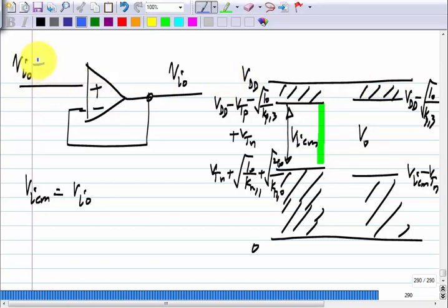Now, in this particular case, you have to look at this again, now we apply a signal. So, Vi0 plus Vi, what will be the output? Approximately the same. Okay, let us ignore that Gm by Gm plus GDS, that number. So, this is approximately Vi. Okay. So, what are the conditions you have to satisfy? Yeah. So, now what is the input common mode voltage when the signal is applied? What is the common mode input of the op amp when the signal is applied? No, the total common mode voltage, what is it? It is just the average of these two, right? It is Vi0 plus Vi.